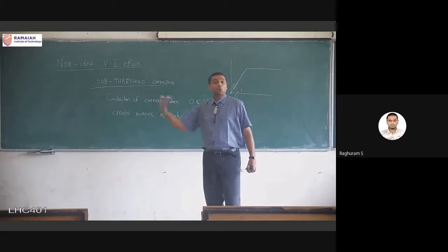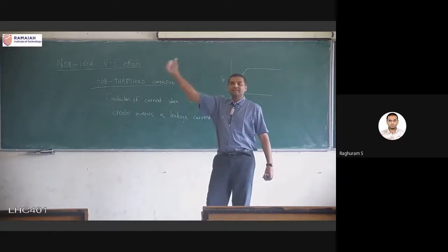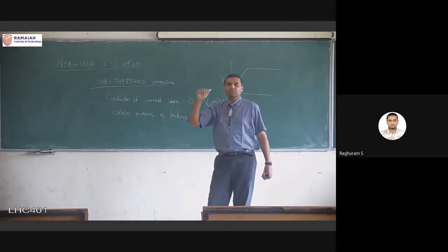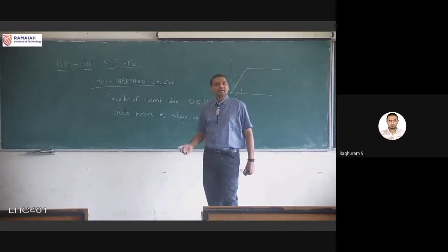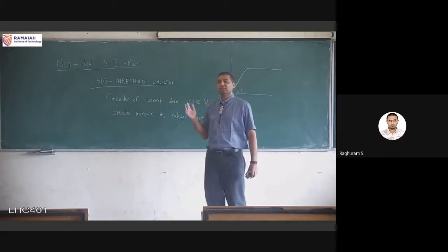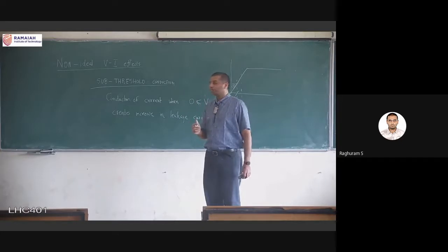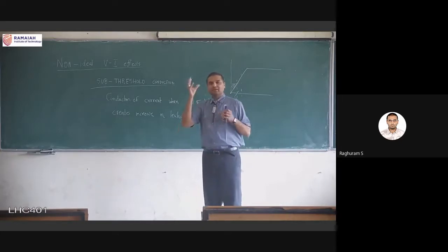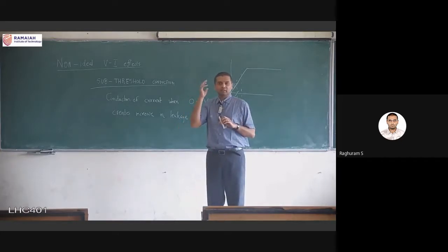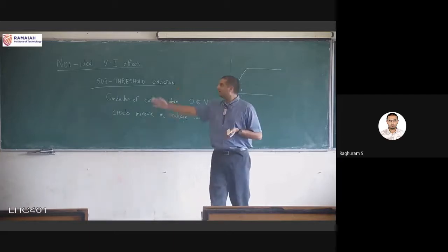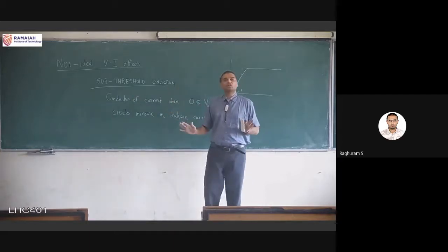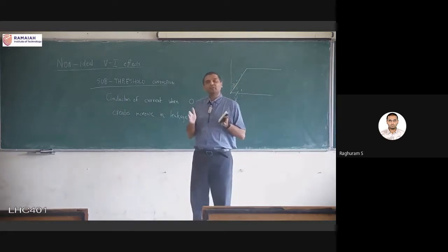Similarly, you might want to open a door. So there will be a signal that is sent to a mechanical relay, because whenever you're thinking of things like door, etc., there should be a relay, right? And relay is a mechanical device and it operates at a much lower speed compared to our electronic devices. So in those type of situations, the whole circuit, that is our central automation circuit, the electronics behind the Alexa or the Google Nest, that whole system is designed in sub-threshold voltage only. That is, the power supply itself is 0.2 volts.